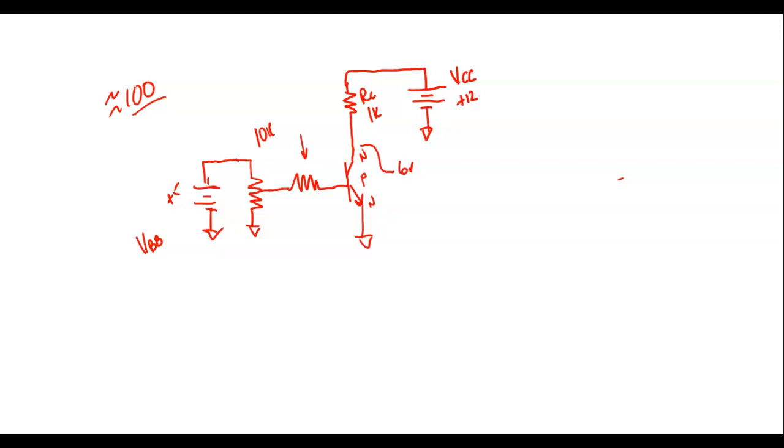Okay, but about the circuit. That's a good point, but about the circuit. Well, we know how much. You're right, but I don't know the resistance of the transistor. The problem is the transistor is a dynamic device. It varies, but I do know that 1K. I do know I have 12 volts on one side of it, and I do know I have 6 volts on the other. You understand? So how much voltage is being dropped across RC?